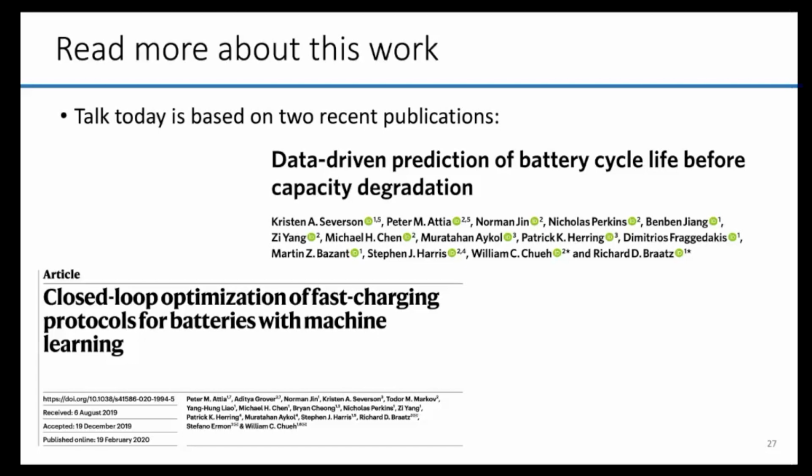I would say no, and that relates back to that idea that the multi-step charging protocols are typically monotonically decreasing in constant current, with a thought that would optimize against plating, and that's not what the optimal experimental design found, and that was validated in additional experimentation that the optimal experimental design identified protocols did perform well.